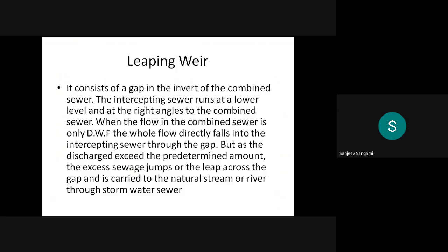But as the discharge exceeds the predetermined amount, the excess sewage leaps across the gap and is carried to a natural stream or river through a stormwater sewer.